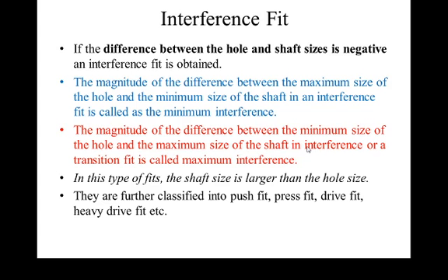Now the next terminology is the interference fit. If the difference between the hole and shaft sizes is negative, then that type of fit is called the interference fit. Again, there are two terminologies, minimum interference and maximum interference.